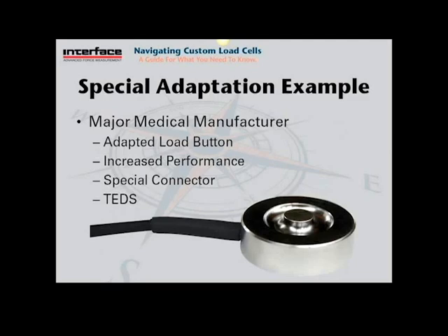We added a connector that was an ultra miniature connector to interface with our equipment. And we also added a TEDS chip. TEDS is Transducer Electronic Data Sheet, which is a memory chip that is put into the unit, and it records all the calibration data and when it was calibrated and things like that. That is kind of similar to the OEM applications where you want a standard output. Well, in this case, you don't need a standard output because the calibration table is built into each load cell, and the user can then just plug this load cell into their equipment and automatically calibrate it.